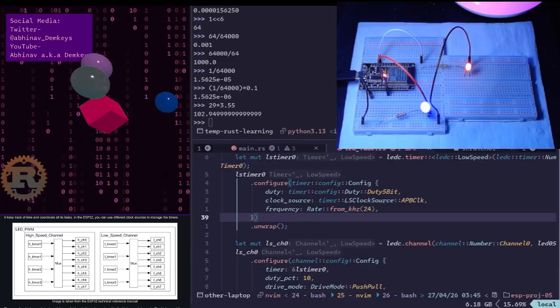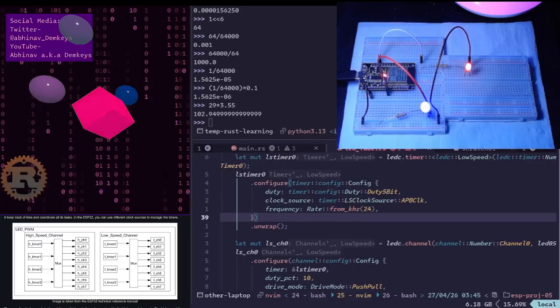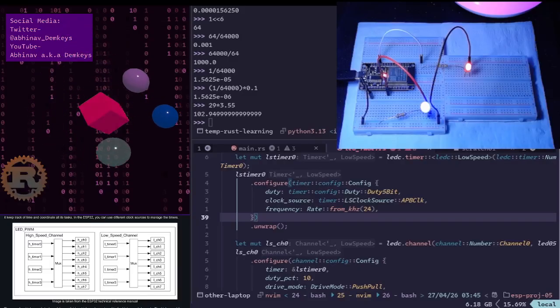So it sends a write command across the bus to a specific address, which is the PWM register. The PWM hardware receives that data and stores it in its local latch, a type of memory that holds its state. Once the data is latched, the CPU can literally be disconnected from the bus or powered off. The PWM hardware is now self driving.